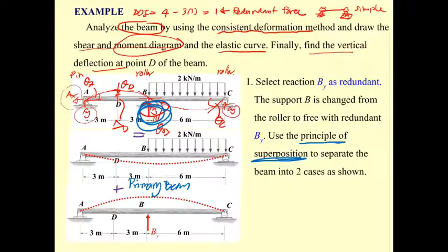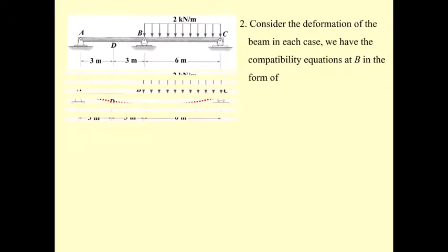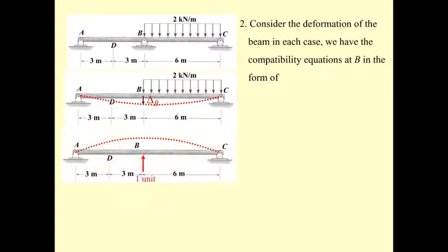And what we have is the deformation. We are going to concentrate on the deformation or the deflection at B. So this one is delta sub B. And this one is going to be F sub BB, the deflection due to the point load at B, due to the load applied at B. The first B is the point of deflection.